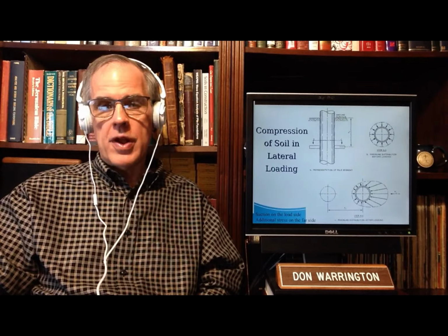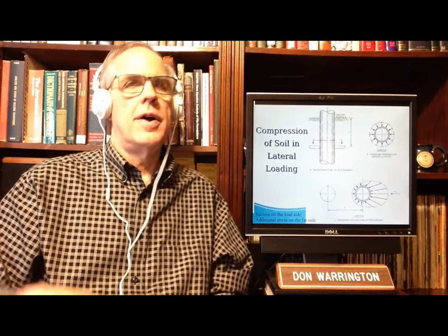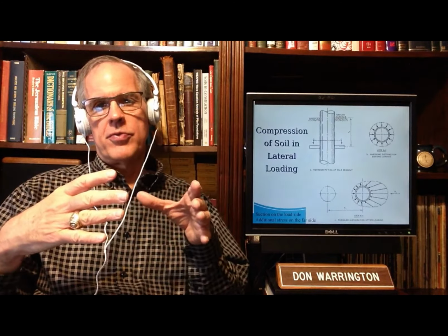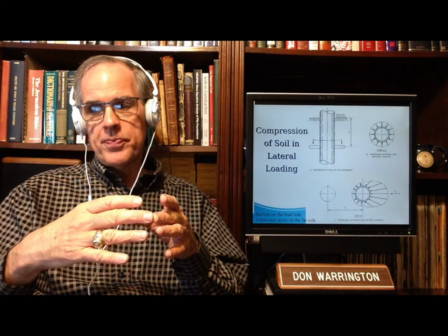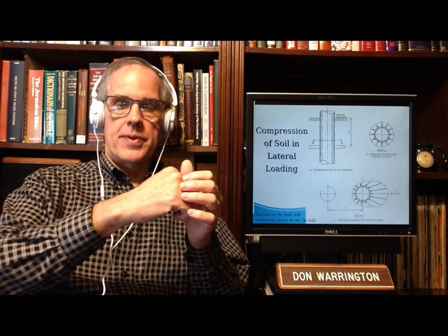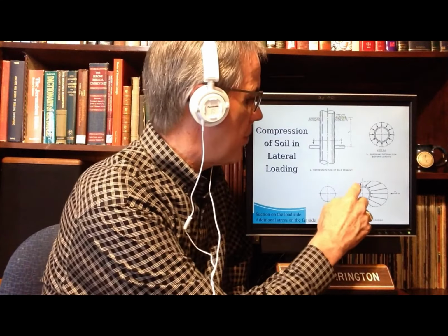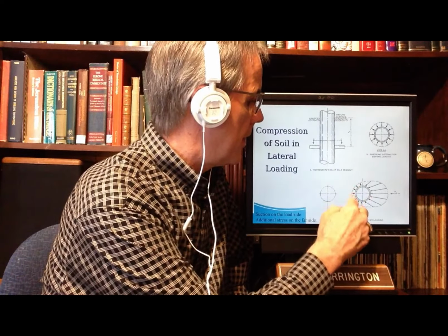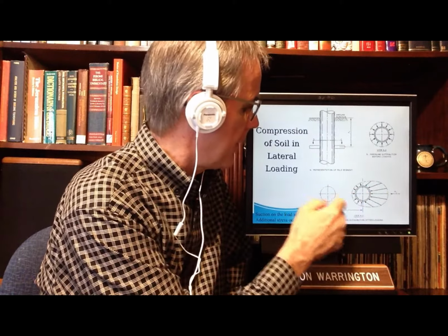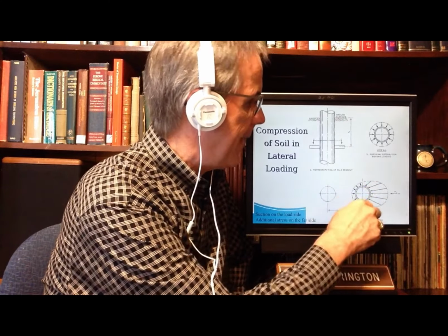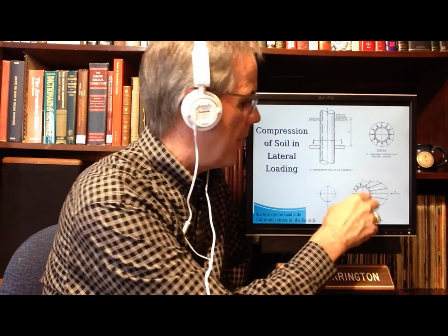Before loading, you have a nice even pressure distribution. You have your horizontal pressures, which are generated by your vertical pressures. As you push the pile, what happens is that you compress the soil on this side, in the direction the pile is moving, and the soil on the other side expands to some degree, or actually in certain cases it will break away from the pile.